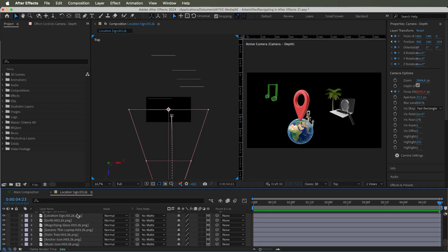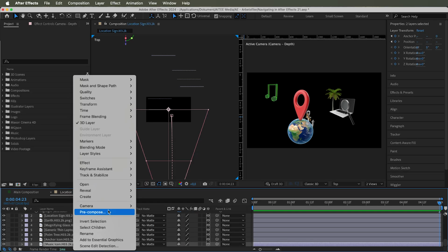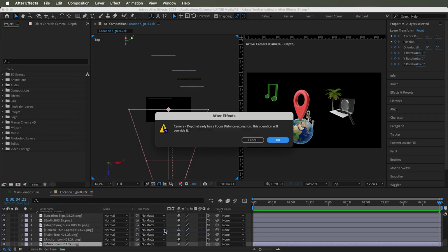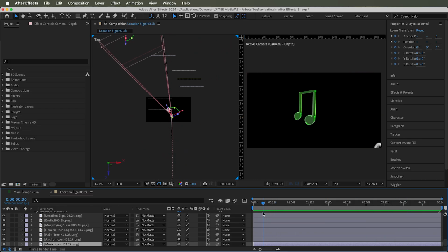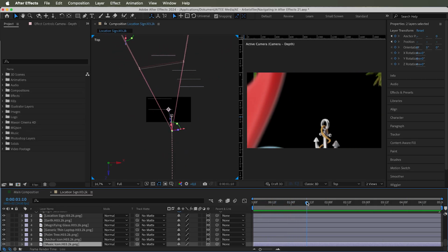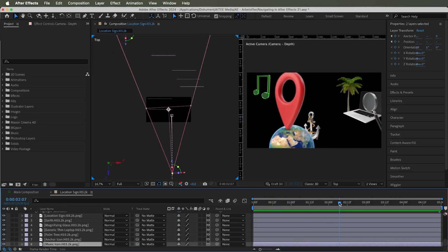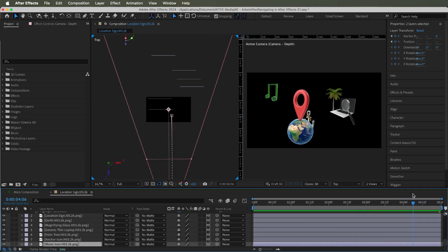By marking the camera and another layer together, you can go into Camera again and choose Link Focus Distance to Layer, and that focus distance on the camera will now always follow and adapt to the movement of the layer, always keeping it in focus.